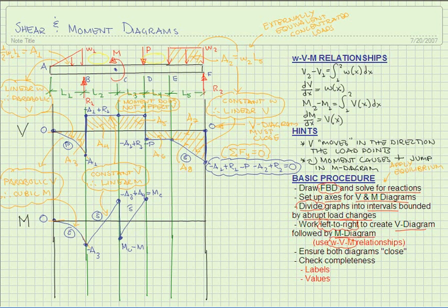So we again have a linear slope, and this gets us to the moment value at D. Again, just continuing on with our addition and subtraction routine. Now we have a negative area, so a negative change in moment, which would get us to the moment at E.